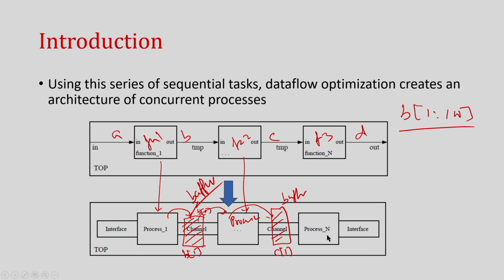Similarly, process 3, which knows that C0 was available in an earlier cycle, can now take C0 and produce D0. In the next clock it understands there is a C1 and it processes D1. So, what is going to happen in this way? If you put an intermediate buffer between these processes, each process works independently, and whenever it produces some data, it does not send that data directly to the next module; rather it puts it in the buffer in between, and there is a handshake method.